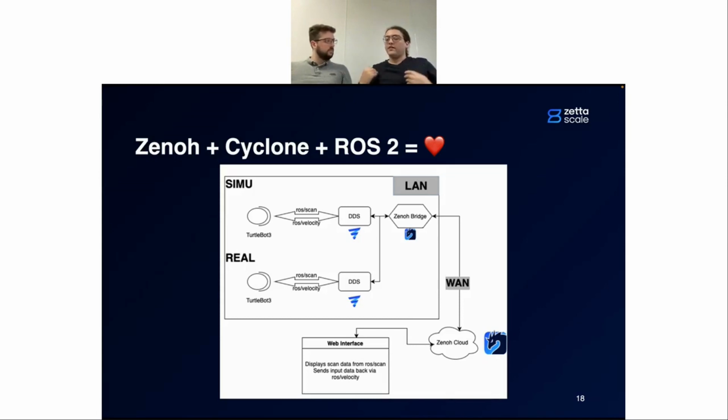And then in that cloud instance, they had a web interface set up where they could teleoperate that remote ROS instance, the robot that was present there live. And they also did some other interesting stuff there, like with the Zenoh plugins, they had an MQTT plugin hooked up. So you could use buttons and stuff to control the robots over MQTT, translated into DDS land.